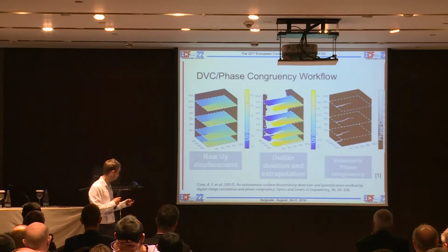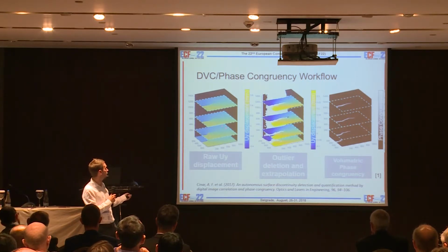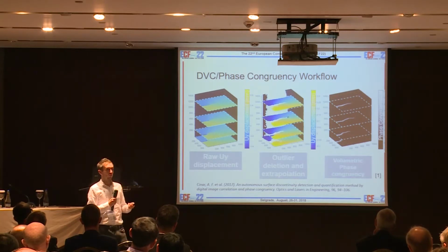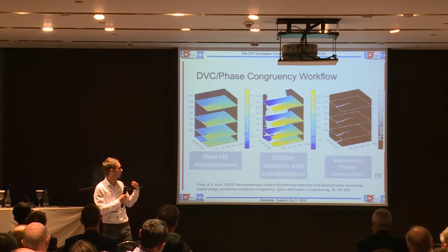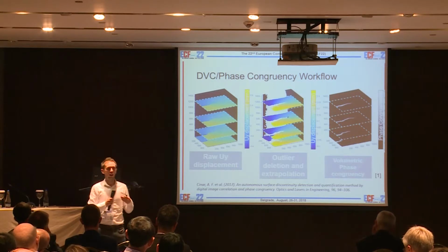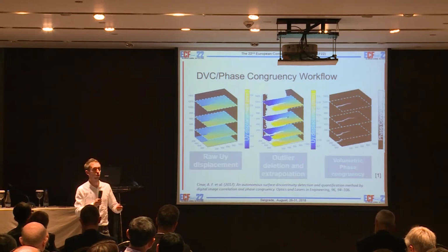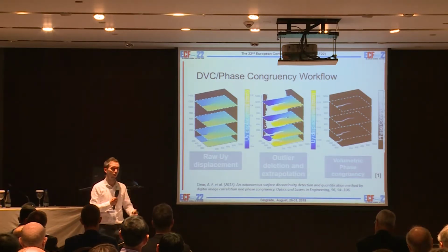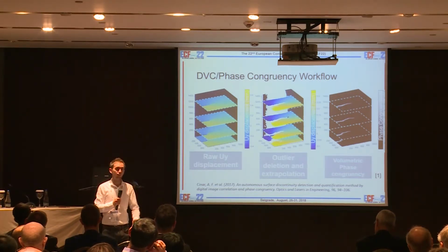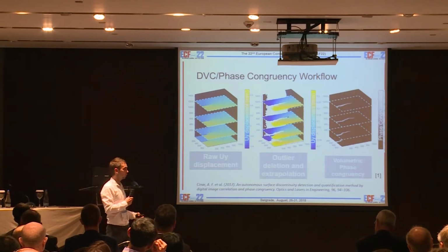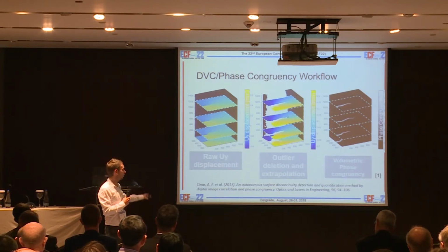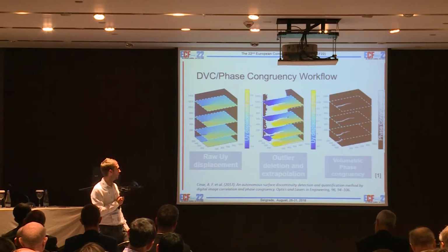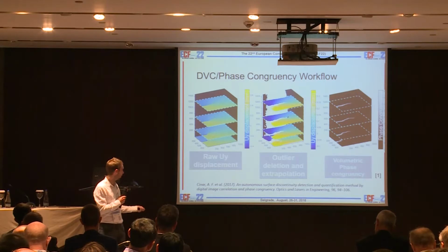That gives us what we can see here, which is our raw displacement field. The pre-processing doesn't stop there. We have to go through a process where we do outlier deletion and then extrapolate those values before using something called volumetric phase congruency, which is another technique we had to develop as part of this process. This was covered in Ahmet Chinar's PhD thesis and some of the associated papers, which you can find here.